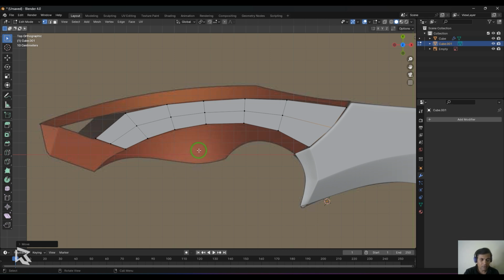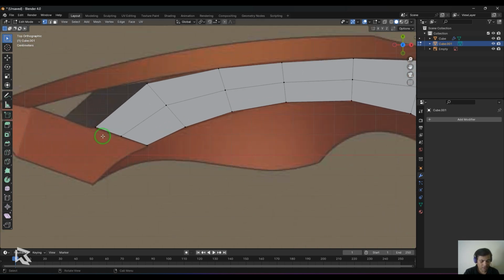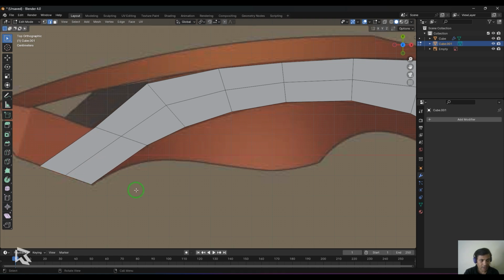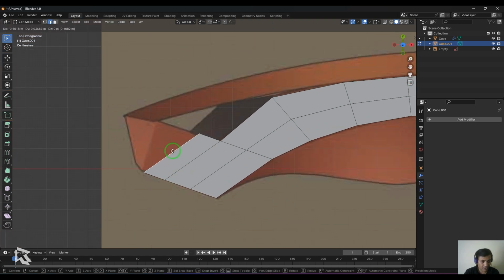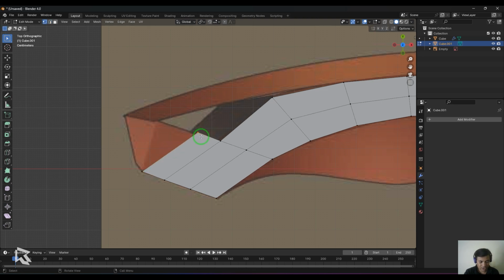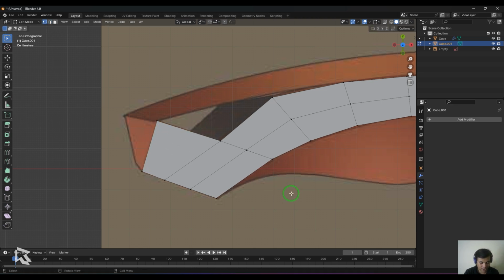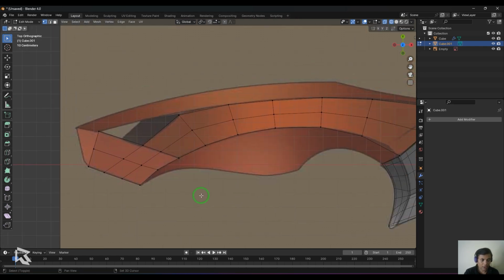So what I need to do is extend those points here. Okay, so I select these 2 edges and press E, and then I get those lines like that. Then select that one and press E, and then press 1 for the vertex mode, and press G for the move tool, and then start placing those points at that level. You can press Control R and then select those points and match the outline here.